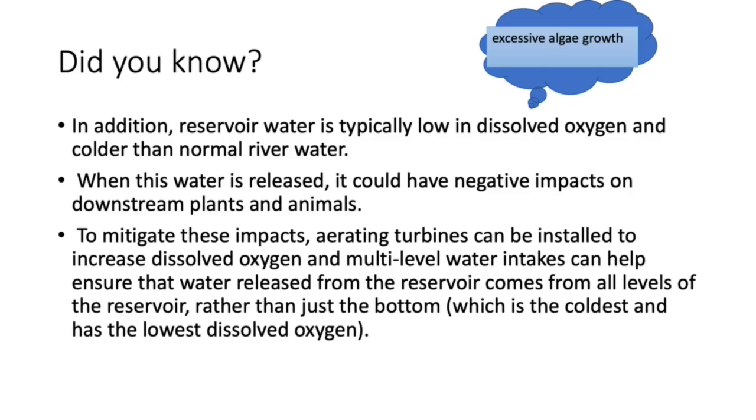Hence, to reduce these impacts, aerating turbines are installed to increase the dissolved oxygen, and multi-level water intakes can help ensure that the water released from reservoir comes from all levels of the reservoir rather than just the bottom, which is the coldest and has the lowest dissolved oxygen.